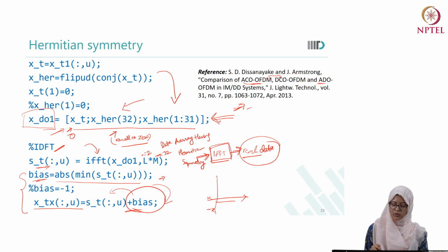So you are just going to subtract this bias. Obviously this data will be multiplied with the channel gain and AWGN noise will be added. After that, from whatever received data you have, you will do the equalization and then subtract this bias.